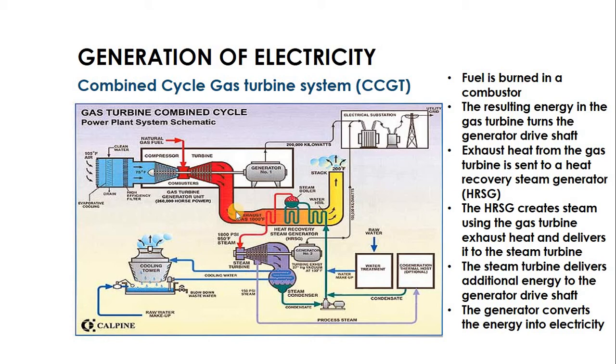So as you can see here in the exhaust, we have another piping system containing water. So the hot exhaust, as it's going out, heats up the water in the pipe, produces steam, and that steam goes to drive a steam turbine which is coupled to another generator, and these two generators are synchronized. At the end of the day, the power from here adds up to the power here, and you have more power. If you remove the steam turbine system from this place, you only have the power generated here.